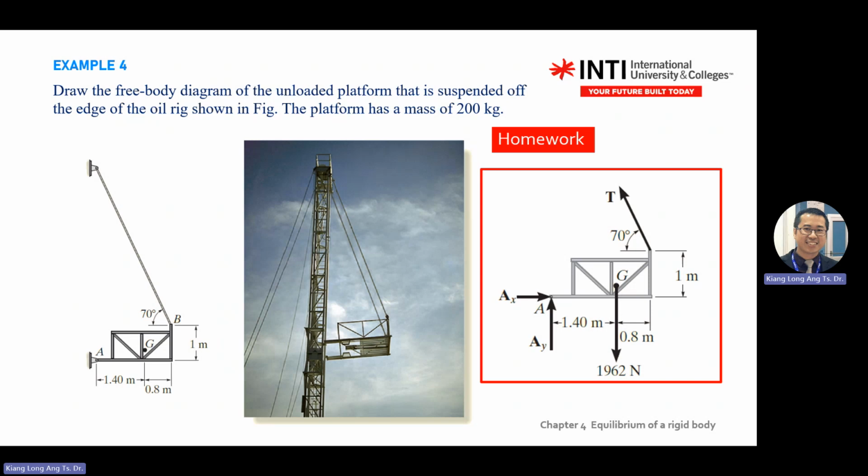Here got two unknown. You don't want to solve these two unknown. Put your finger there, do moment at point A. Then you can solve what is the tension at T already. Of course, you can put moment at T also, if you want. But here got angle. We try not to disturb the angle.